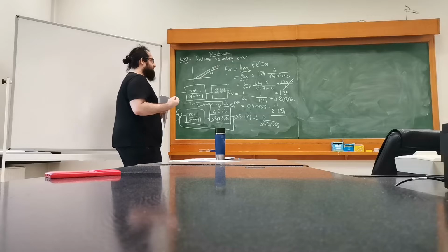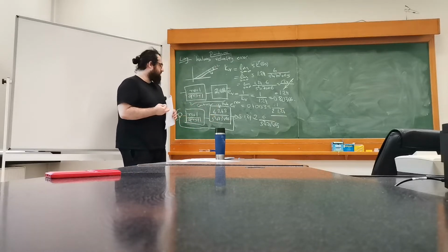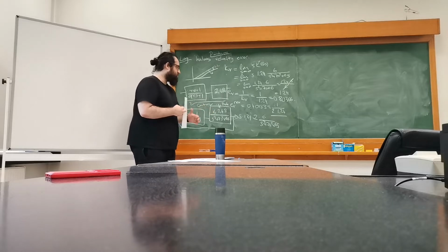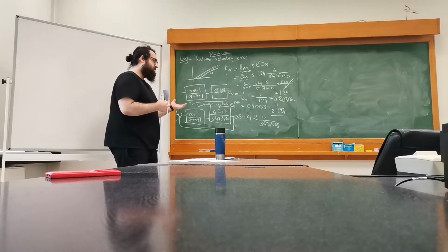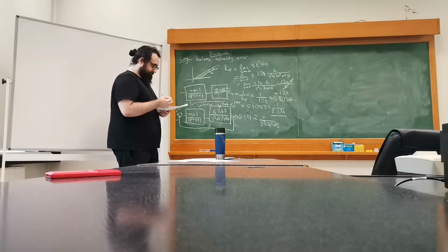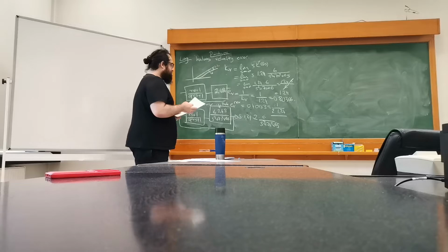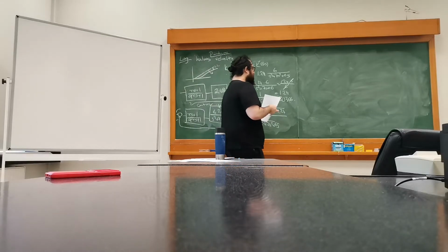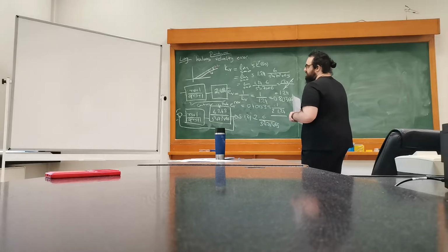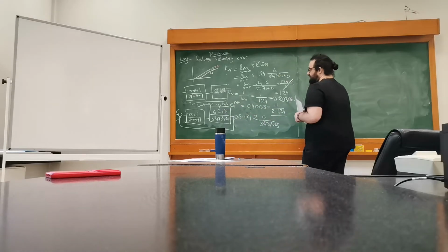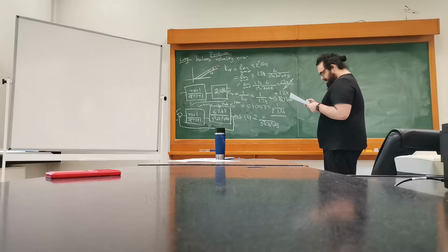We can use the original system because the only thing that changes here is the gain. So we can just multiply that with 2.48, and the angle condition is the same. So it doesn't really affect the Bode graph that much, but it's up to you. If you're in an exam and you don't really have the Bode plot corresponding to the system, then you have to work your way out on your own.